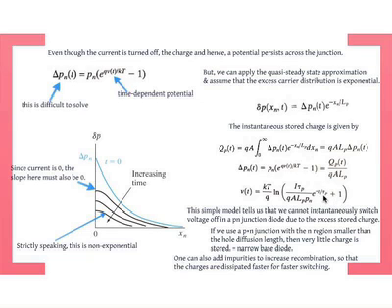So this simple model essentially tells us that, of course, first of all, you see a time dependence here. You have an exponential time dependence here, which is within a logarithm. So it's not a simplistic exponential. So exponential can be fast, but it's not just that. So it's exponential within a logarithm. So it can be slow, which is a problem, right? You want these things to switch fast. So voltage cannot instantaneously switch in a p-n junction diode due to the excess stored charge.